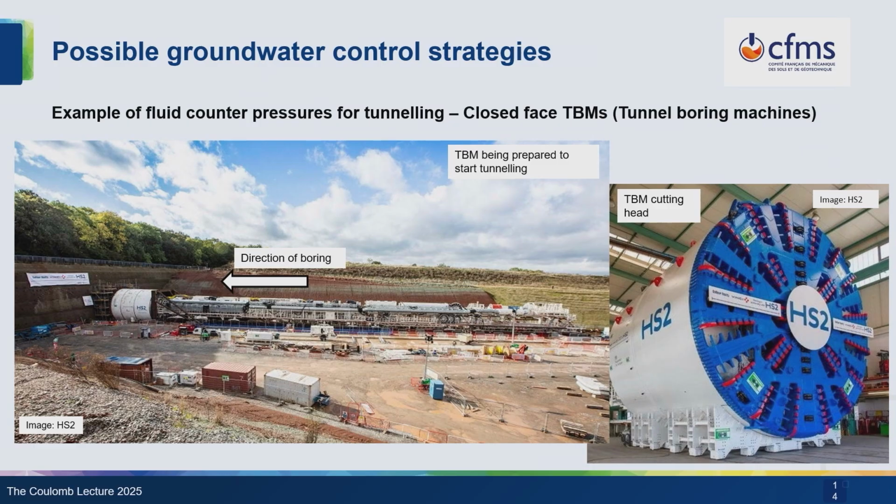This method is the basis of most closed-face tunnel boring machines, or TBMs. This is a picture from the HS2 project in the UK. It's actually the Long Itchington portal. I think this tunnel is completed now. And this is the very long tunneling machine. But here we have the element that deals with fluid counterpressure.